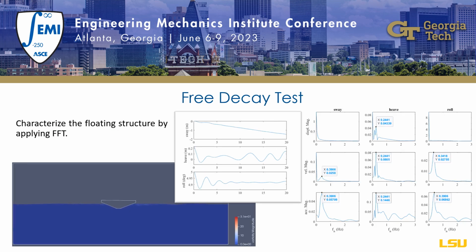Therefore, we did a free decay test. The structure has an initial 5-degree pitch. The response decays slowly due to the viscous effect around the embedded surface, and also the induced waves take away its kinetic energy. Then we can characterize the floating structure easily by applying the fast Fourier transform.